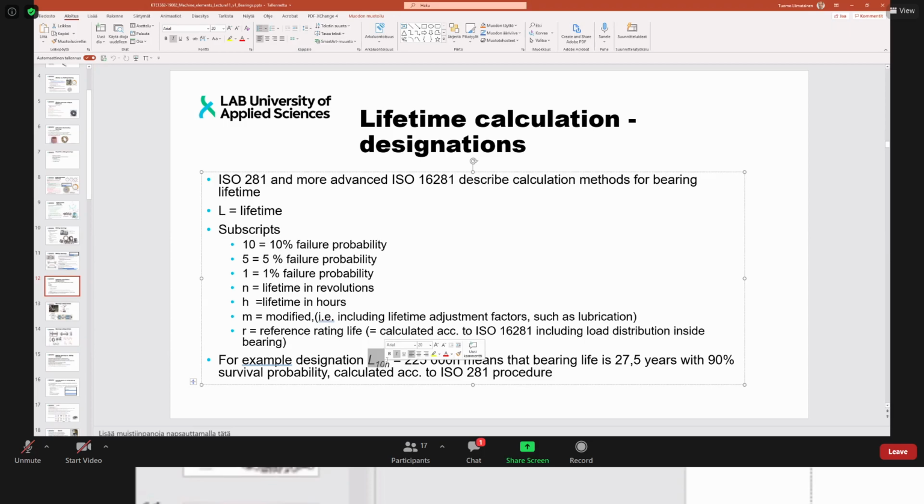And someone might consider, okay, 10% failing bearings, it's a lot. Yeah, maybe. But when you consider the Gaussian distribution, in order to obtain higher statistical reliability for the bearing system, it would probably mean very high over-dimensioning for the bearing system in order to gain better statistical probability against failure.